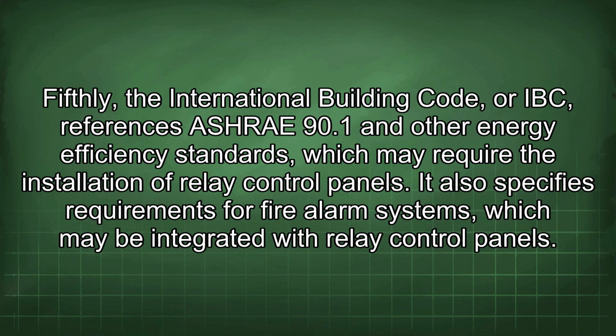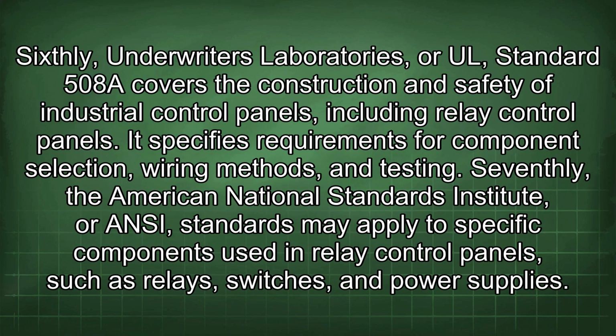Fifthly, the International Building Code, or IBC, references ASHRAE 90.1 and other energy efficiency standards, which may require the installation of relay control panels. It also specifies requirements for fire alarm systems, which may be integrated with relay control panels. Sixthly, Underwriters Laboratories, or UL, Standard 508. It covers the construction and safety of industrial control panels, including relay control panels.